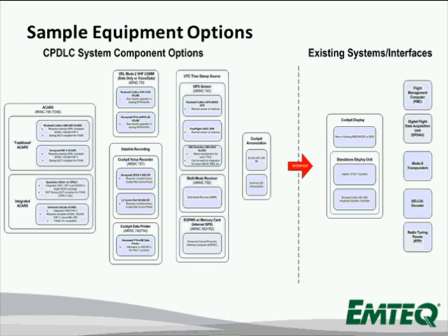like the Spectralux D-Link Plus with CPDLC and the Universal UniLink ACARS, which both have an integrated VHF3 communications transceiver in the unit. The Spectralux D-Link Plus is essentially an all-in-one box. It's an MCDU with an integrated communications management unit, so it's a display unit with the internal communications management unit as well as the VHF3 transceiver, all in one box.